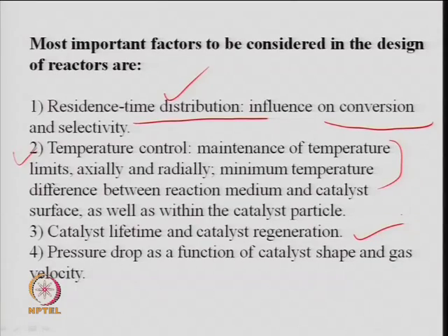So, that the pressure drop should not exceed, but when you have larger size particles, the mass transfer problem will arise. So, you have to control that there should not be any mass transfer limitation, and simultaneously there should not be very high pressure drop. So, the particles should not be very fine also. These are some issues which need to be considered when you select a reactor and the catalyst for the process. So, with this I stop here and I will continue in my next lecture. Thank you.